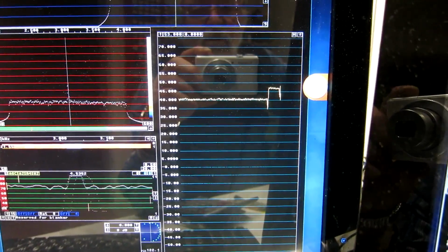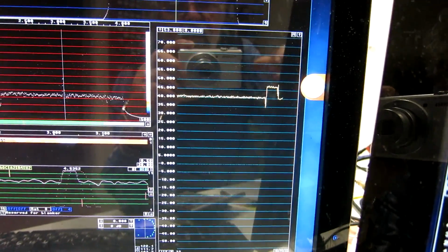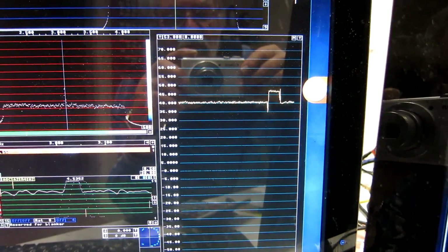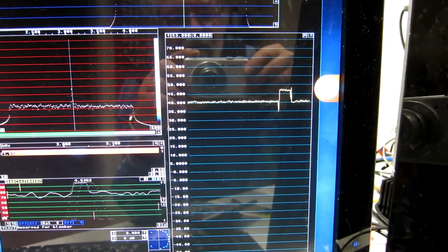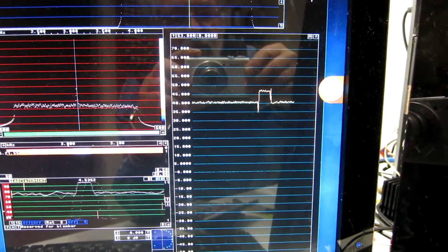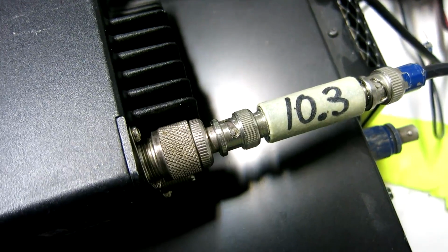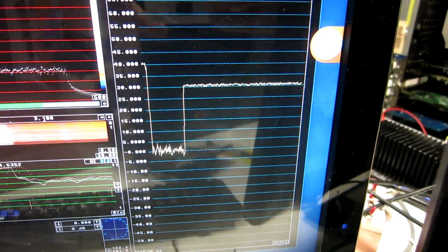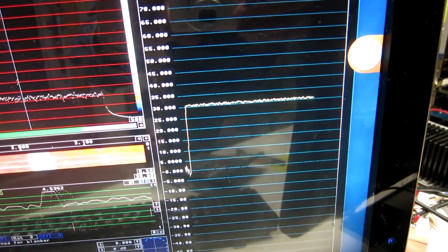So it would be unfair to compare with it. I will insert an attenuator to bring it to the same noise figure as I had in the ft1000 and also in the Perseus. A 10 dB attenuator brings signal to noise ratio back to close to 30, where I have been having it during these measurements.